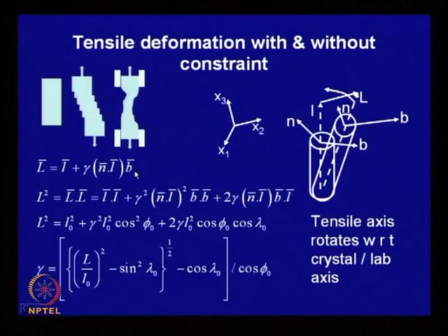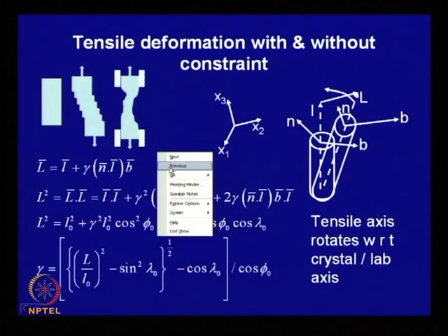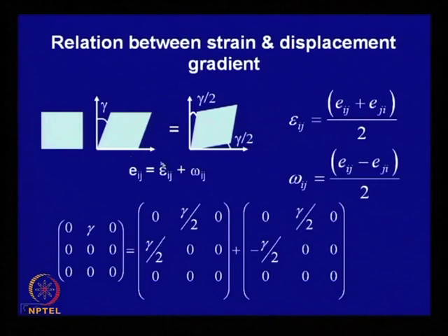So, if you go back here, how do you find out this shear strain? This is the plane, you can see this is the slip plane, the normal is this, and this dot product will give you this. This is the slip vector and this is the plane normal.